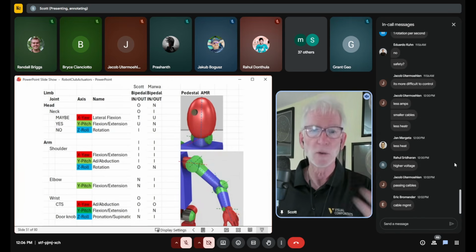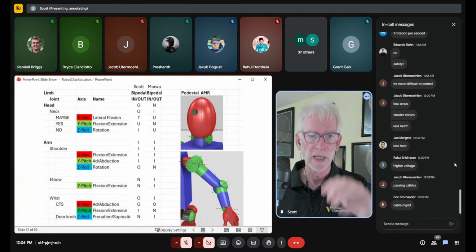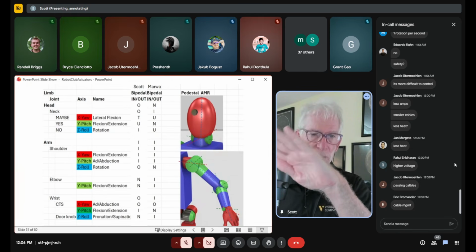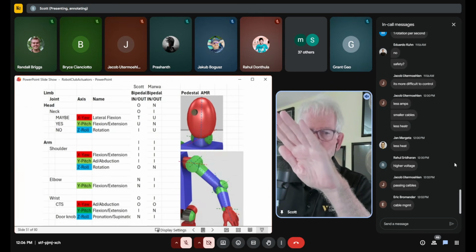So you could argue, oh, which ones do I really need, this joint or that joint? Could I get by without it? I've argued before, and as everyone notices, that your wrist joint doesn't move very far in the yaw. It has very little movement there. It's probably the least important of all the joints. So if you're going to throw a joint out, you might start there.